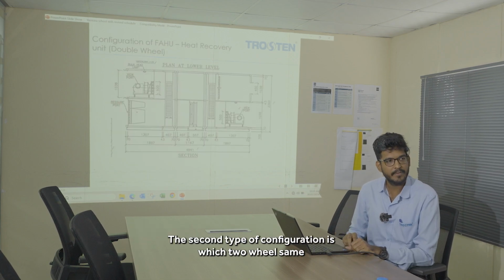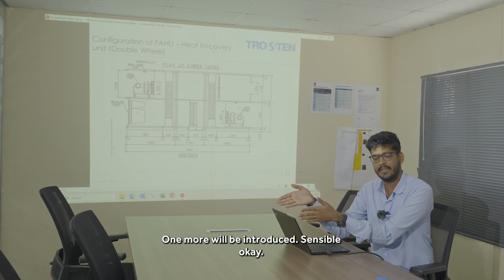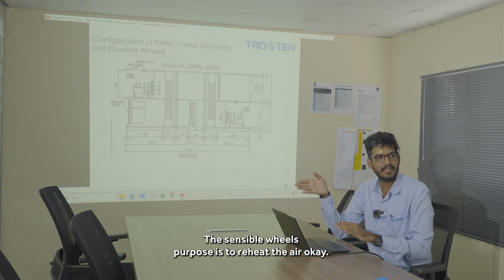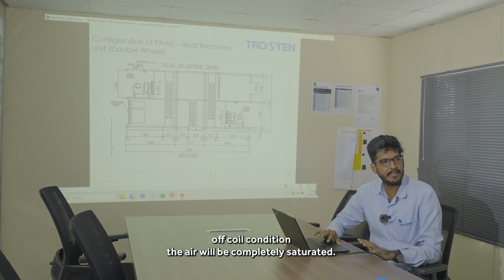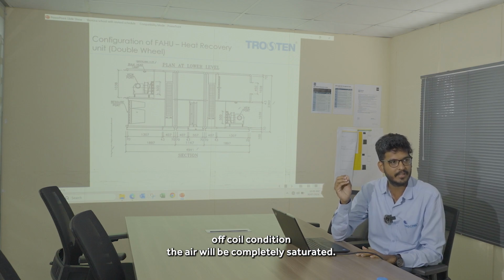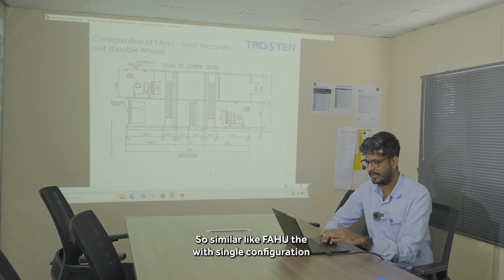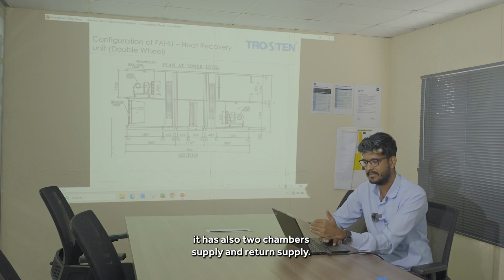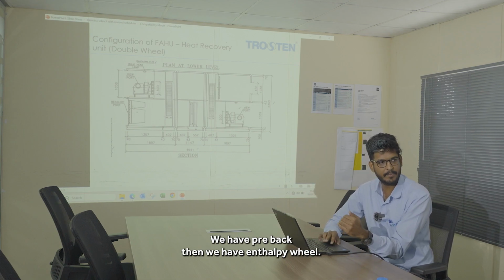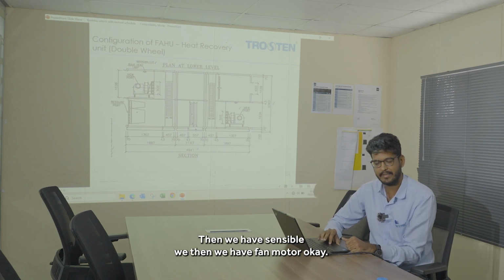The second type of configuration is with 2 wheels. The same single wheel is there, and we introduced one more wheel, the sensible wheel. The sensible wheel's purpose is to reheat the air. In off coil condition, the air will be completely saturated, so the RH will always be in the range of 90 to 98%. Similar to the single wheel FAHU, it has 2 chambers, supply and return. In supply, we have pre and back filters, then the enthalpy wheel, then the cooling coil, then the sensible wheel, then the fan motor.